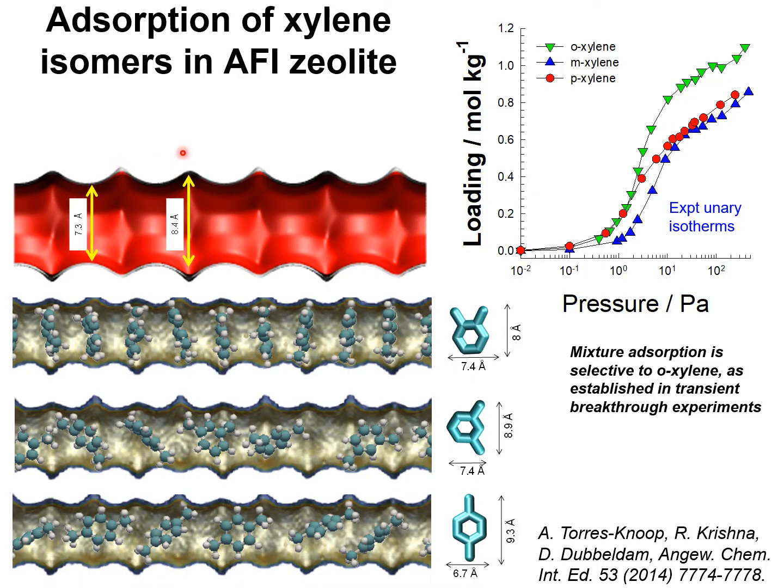Since the adsorption selectivity in favor of paraxylene that is obtainable with barium X zeolite is of the order of 2, it is of industrial importance to examine whether alternative materials such as zeolites and MOFs offer improvements in paraxylene selectivity and uptake capacity.